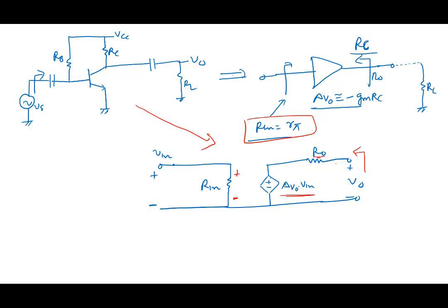So now with this, once you take an amplifier like this and you know Rin, you know AV0, and you know R0. For us, the value of Rin was 2.6K, R0 was 2K, and AV0 was minus 38. So we found these values out, right?